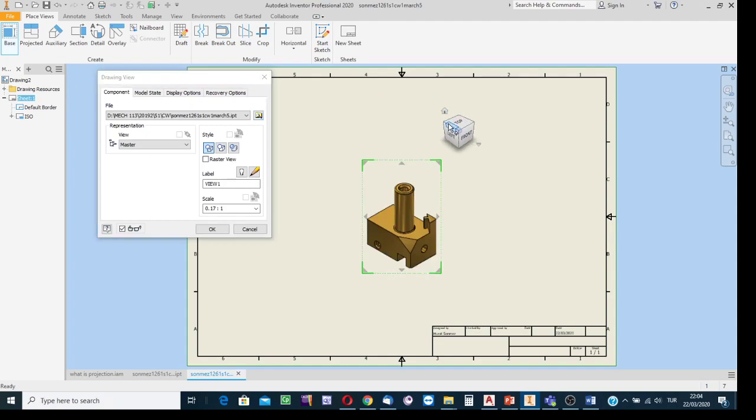Okay, well, clicking on the corner of the orientation cube enables you to see the simulation three-dimensionally, and then much more easily you can see which side you selected as the front side of the object, and then see the parallel surface of the orientation cube. It is parallel to the front side, and make a click on that surface. Then Inventor can understand that you're going to create that side view first.